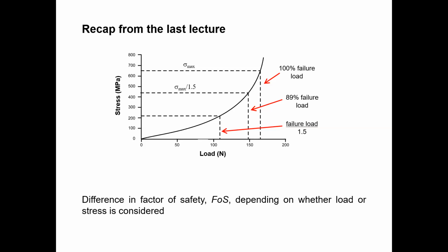If you remember, did you do some exercises? Some questions? If you did, you can recognize what I'm explaining. So then you calculate the stress with the KF, and that value and the strength value without KF should be equal. Then you can find out the maximum load, the 10 to the power 6 cycle load value, and you can calculate the factor of safety in this different way.